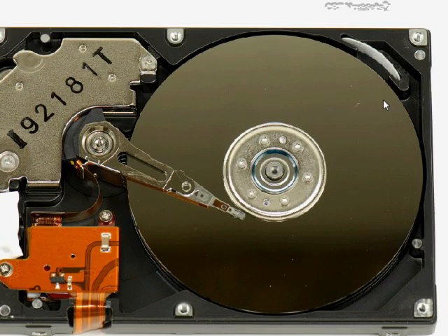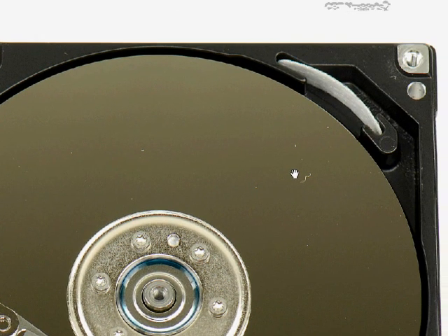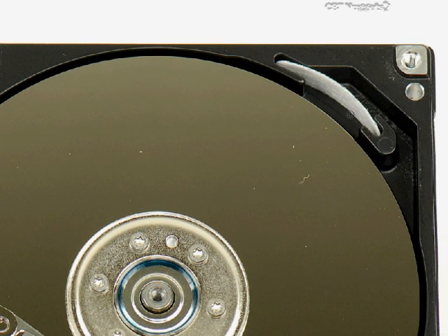And then we also will take another look at this hard drive, and one thing I want to point out is in the corner of this, and this is not an A+ exam item, but just so you know, as the hard drive spins around at either 5,400, 7,200, or 10,000 RPMs, it generates its own wind, and the hope is that it'll cast off any contaminants or particulates that may have rested on the platter here or somehow gotten inside of the hard drive, and they will get caught on this kind of cloth-like material back here. Notice that as the wind comes around, there's a grooved area here where hopefully it'll get cast off and then get trapped back in here or get trapped by this cloth-like material there.